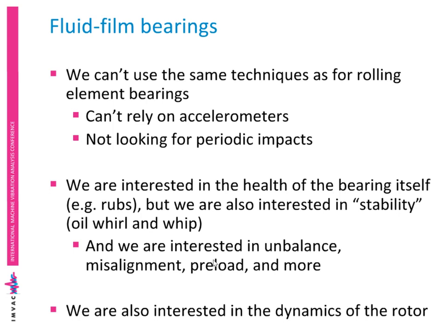Now we are also interested in, let's just call it, the rotor dynamics. With a lot of these sorts of machines, the machine might operate above the critical speed of the rotor. That is, as the machine's running up to speed, the shaft will begin to flex, kind of like a guitar string, you know, strums back and forward. It's resonating. The shaft itself is resonating, and the machine operates higher than that speed. So as it runs up, we are very interested in how it's operating as it goes through that speed.